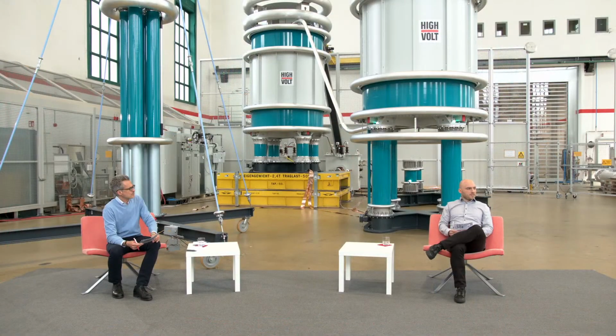Yeah, actually for DC it's maybe not really a solved question. For AC we know that the joints and terminations are mostly the parts where we have PD. Usually the cables are produced, like Marc said, under very good quality conditions, and then in the field one has to build the joints.